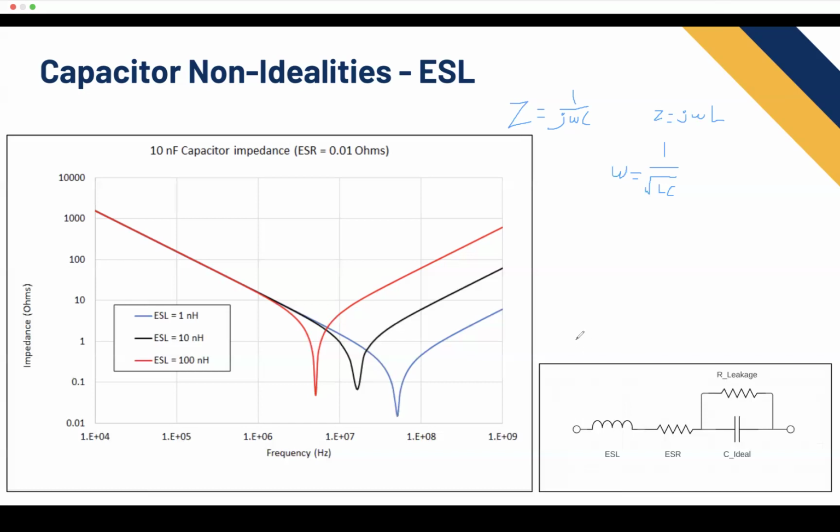But this specific effect appears in this instance as well. Now, the reason it goes down and then comes back up is because if you imagine at lower frequencies, your impedance over here on the inductor is going to be really low, right? Omega's low, L is constant, so this impedance is low. And omega's low over here, so your impedance of the capacitor is going to be really high. So the capacitive term dominates.